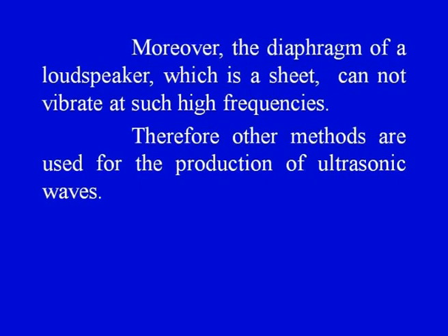This is due to the fact that at very high frequencies the inductive effect of the loudspeaker coil is so large, I mean, the impedance of the coil becomes so large, that practically no current passes through it. Moreover, the diaphragm of a loudspeaker, which is just a sheet, cannot vibrate at such high frequencies.